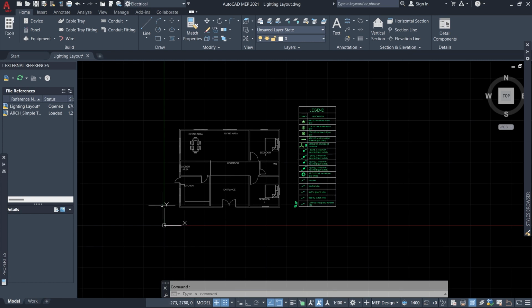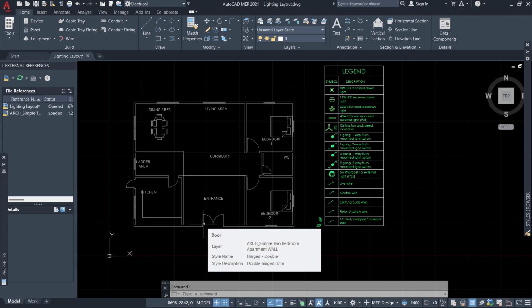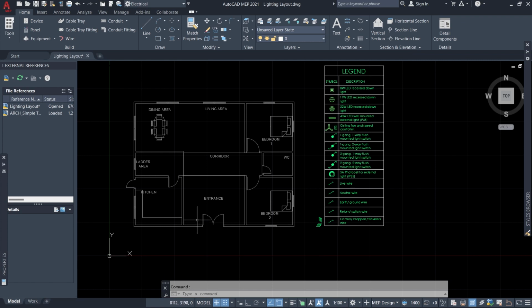Before you put any light in any space, you need the dimensions of the room and the lux levels required for the room. Then you can calculate the lumen levels that a particular room demands, and subsequently tell how many of a specific fixture you can lay out.